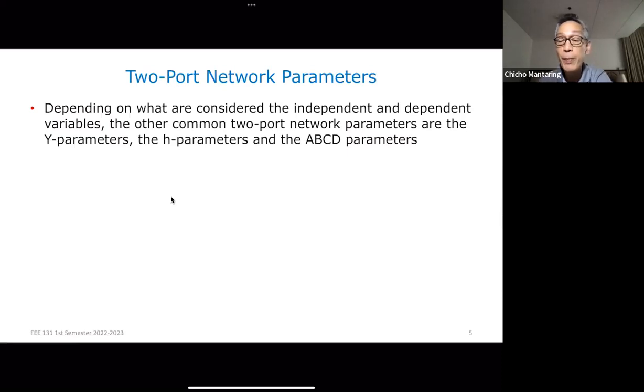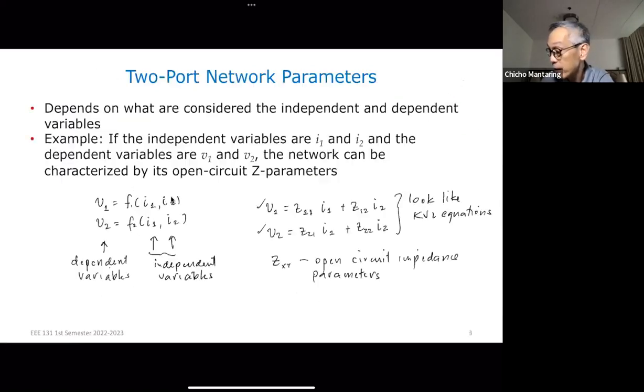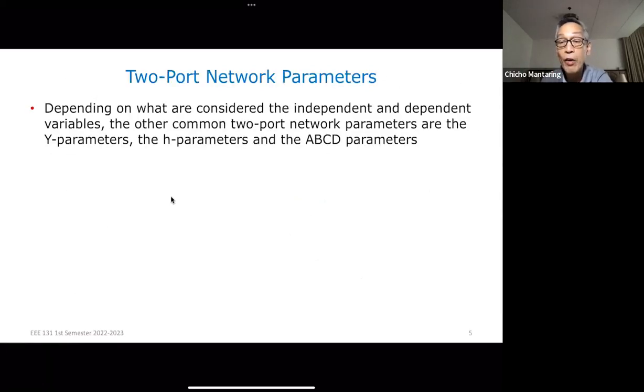And the reason why they're called H parameters is because the parameters describing the circuit are not of a single unit. Some are resistances, some are Siemens, and some are just gains. That's the hybrid parameter. And then you also have your ABCD parameter, which is often used in power systems engineering or electrical engineering.